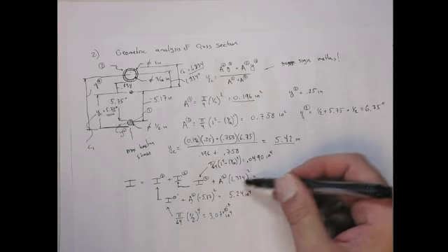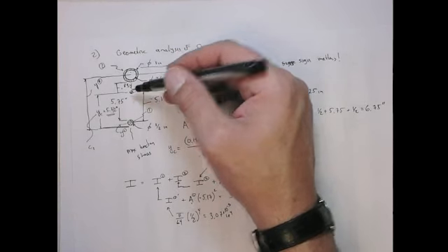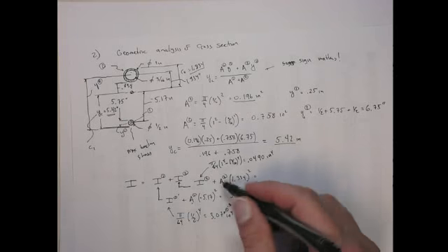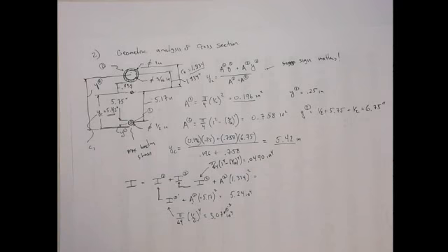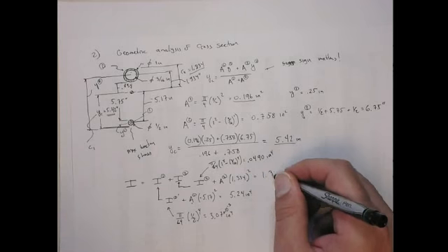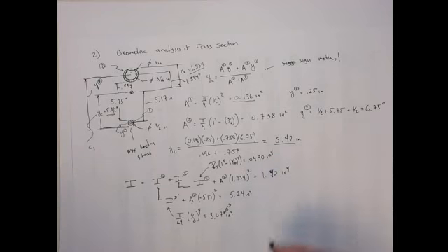And again, this is going to be dominated by the offset, right? So this actual I is not that much, but the I, when you offset it, is going to become much bigger. So this becomes 1.334 squared. Add that, so this term here is 1.35. We add that to the 0.05 and we get 1.40 inches to the fourth.